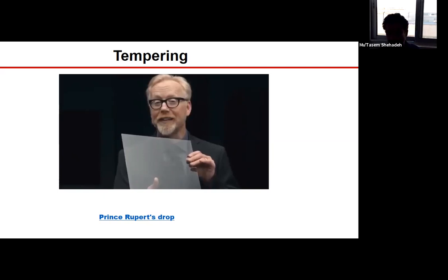So again, it depends on whether we are talking about the solidification process of the molten glass to the solid, or simulating this fragmentation process due to the internal residual tensile stress that was developed inside the core. This behavior again can be simulated using either particle methods or finite element.